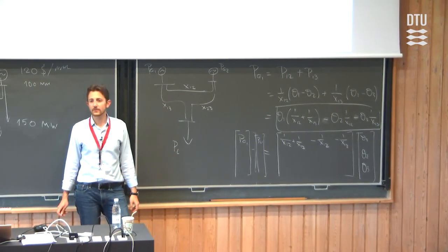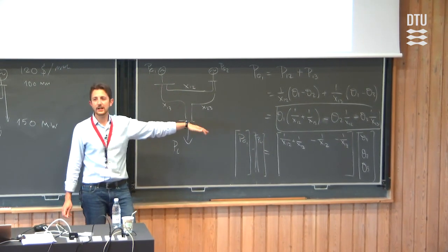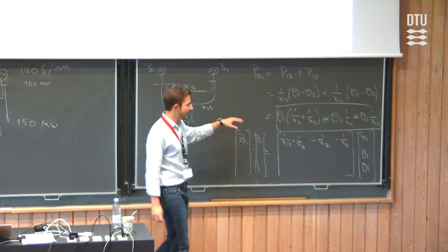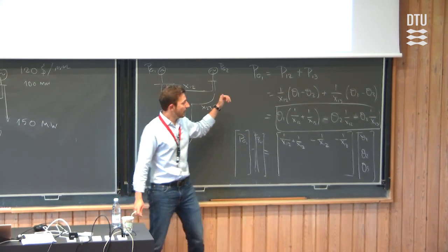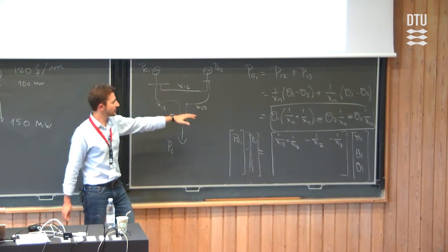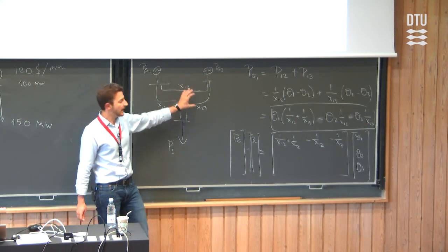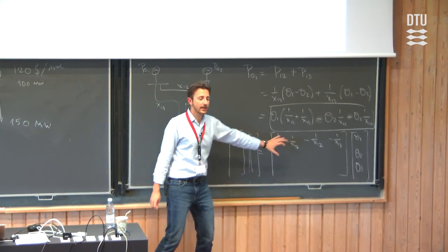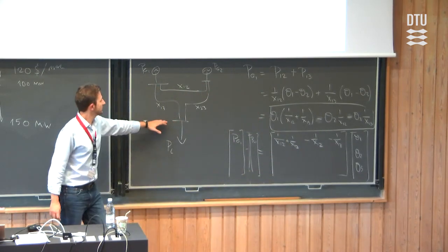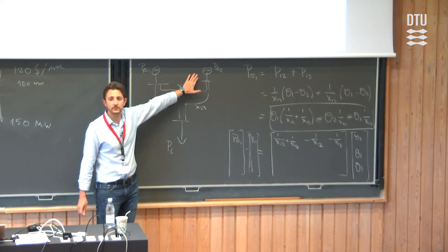So we could actually go all the way and actually build that matrix, but there is a simple rule that you can always follow. And the rule is as follows. On the diagonals, I have all the susceptances. So 1 over x12 is the susceptance, is the inverse of my reactance. I have the sum of all susceptances. So if I go now to, let's say, 2, 2, this is node 2. What's going to be on the diagonal on the second row?